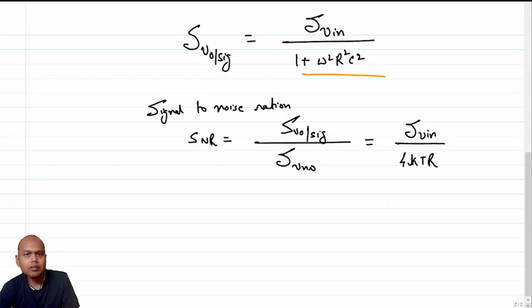It's effectively a filter, right? So if you reduce R, I am changing the bandwidth, isn't it? If I am reducing R, I am changing the bandwidth. So that essentially changes the way the circuit itself works. But let's say I do not want to change the transfer function. What is the transfer function? The transfer function for the first order RC circuit is 1 by 1 plus j omega RC. If I do not want to change the transfer function, but I want to reduce R, then what should I do? I should increase the capacitance by the same factor, right?